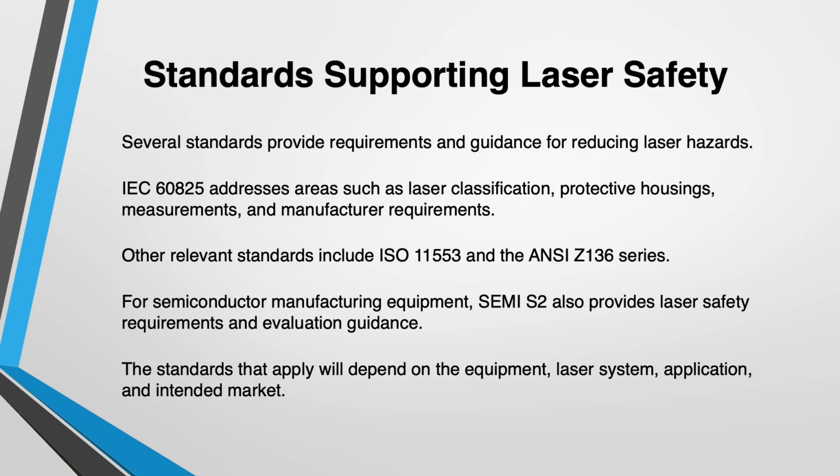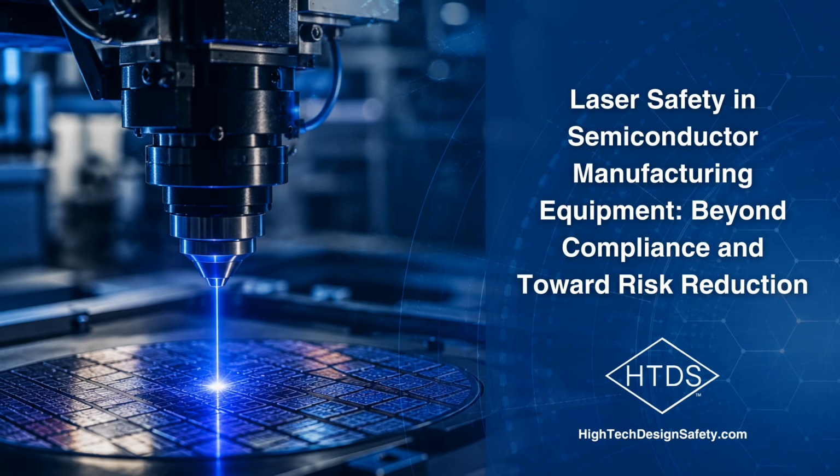Several standards provide requirements and guidance for reducing laser hazards. IEC 60825 addresses areas such as laser classification, protective housings, measurements, and manufacturer requirements. Other relevant standards include ISO 11553 and the ANSI Z136 series. For semiconductor manufacturing equipment, SEMI S2 also provides laser safety requirements and evaluated guidance. The standards that apply will depend on the equipment, laser system, application, and intended market.